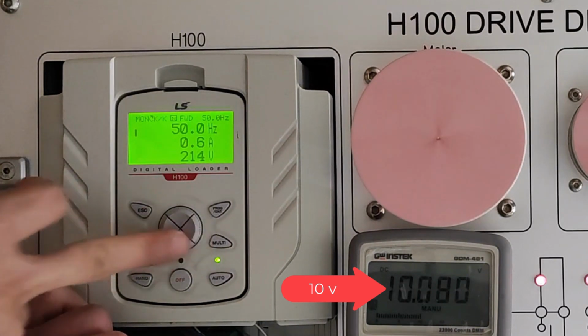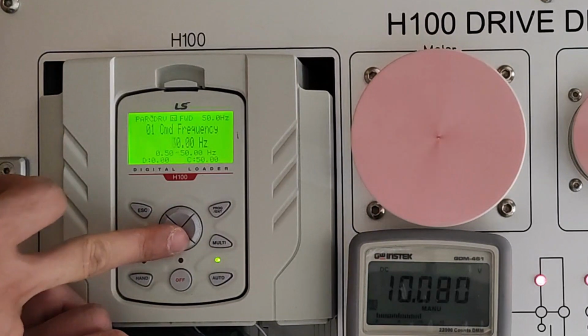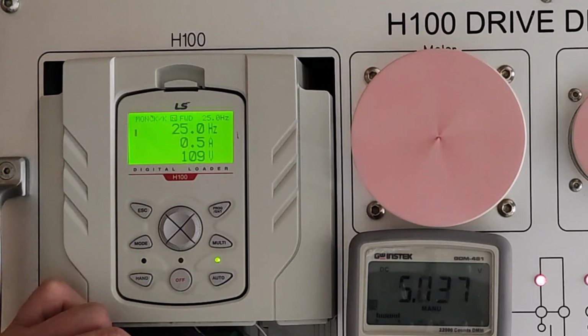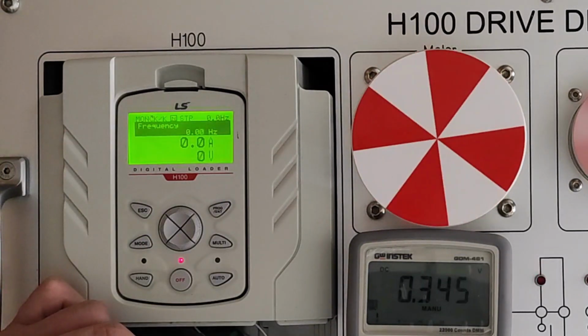Now I'm going to change the frequency value. At approximately 25 Hz, it should specifically output 5 volts. You can see that the voltage value that the multimeter is showing me is 5 volts. If I stop the inverter, then the measured value will gradually go back down to 0 volts.